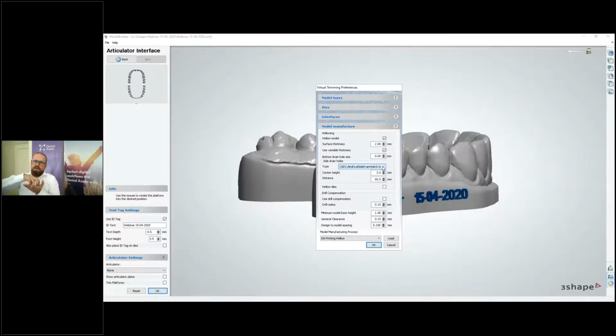So when you pull your object from your resin tank, from your tray basically, there's not a negative force, a negative vacuum that keeps pulling and pulling more. Otherwise you also get another possibility of delaminating or a failed print. Then there's the height of the drains, the diameter of the drain holes, and how far they are apart.